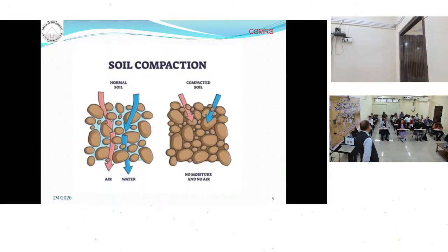So now, soil compaction. What is soil compaction? Anybody? What is the process of compaction? Anybody guess? Removing the voids from the soil. Manually, is there any practical use, or are you all working in the field? Yeah, because in the compaction process, you are using the rollers. In that way, you are increasing the density, reducing the voids, increasing shear strength.